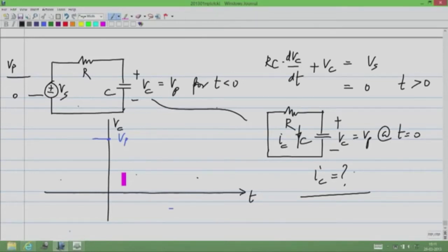That's right. First of all, the voltage across the capacitor and the resistor are the same in this circuit. They are in parallel. So this voltage with this polarity is Vp at t equal to 0, which means that a current Vp by R flows in that direction. So this IC, which is the current flowing from top to bottom in the capacitor, is minus Vp by R.